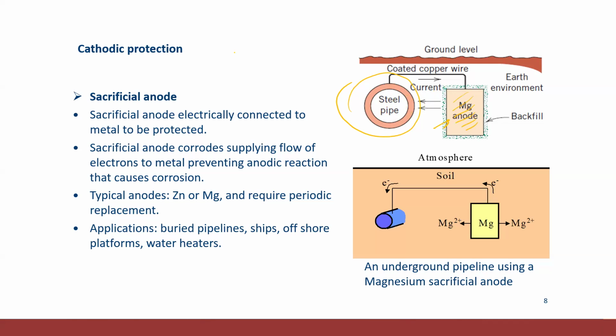And sometimes we have metal parts connected with nuts and bolts. We select the metal sheets or the big structure as the cathode, and we select a material for the nut and bolt which can act as an anode. So the nut and bolt will corrode, but we can replace them easily. If the structure is corroding, it is hard for us to replace. So we only have to replace the nut and the bolt, and we are protecting the rest of the things. Are we good?